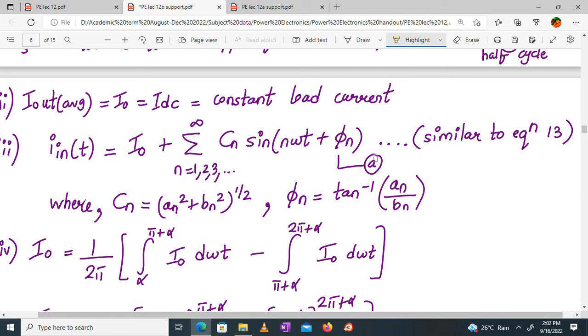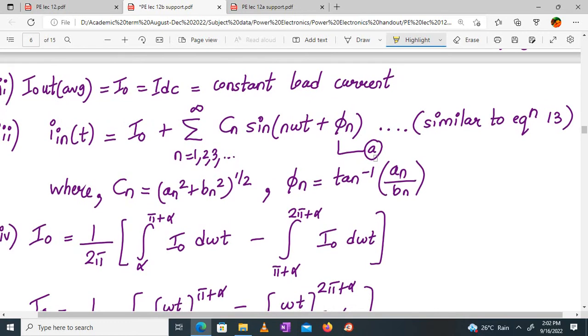The delay angle of the nth harmonic, between the source current and the line voltage. Normally, if it were an R load, current and voltage would be the same, with no difference. Since it is an RL load, the current starts falling, delayed by an angle phi. Further on you will see this is related to the firing angle alpha.